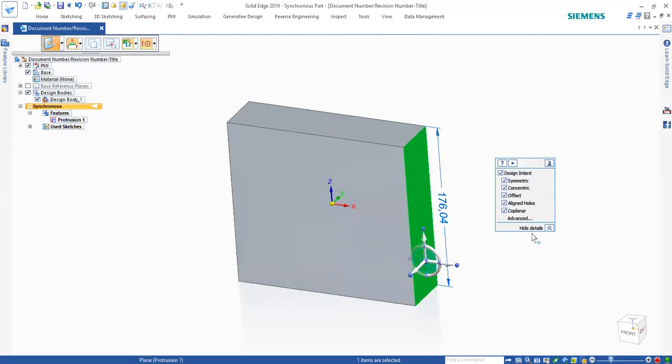You do it with the sketch and then you turn it into a 3D part. So you're coming into a program that you can just edit on the fly on the 3D model. People may sometimes think that you have no control over your design intents, but that is not true in Solid Edge. You have full control over your design intents. And here's the panel you can see here.